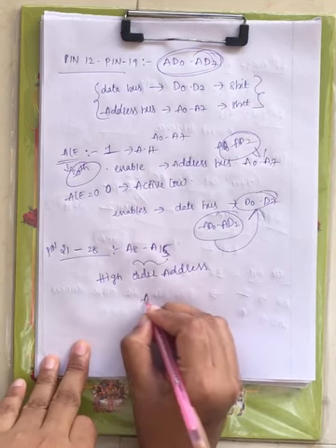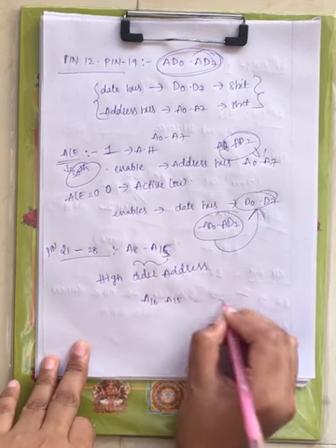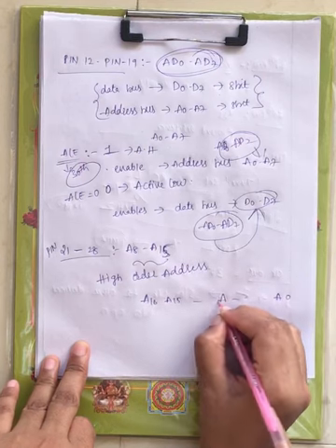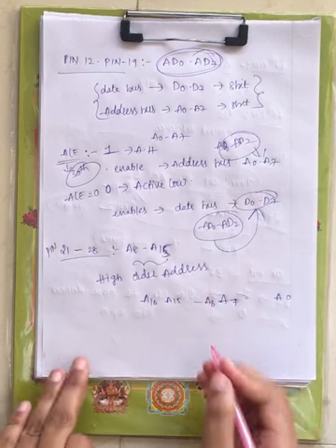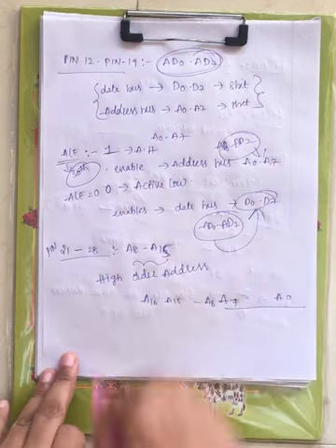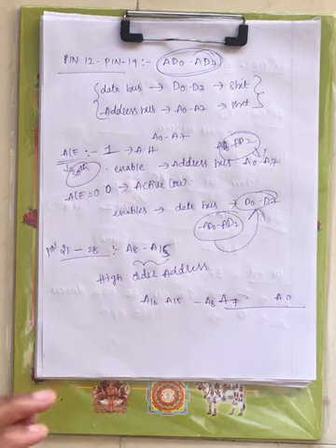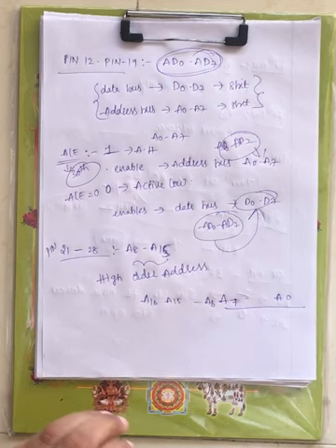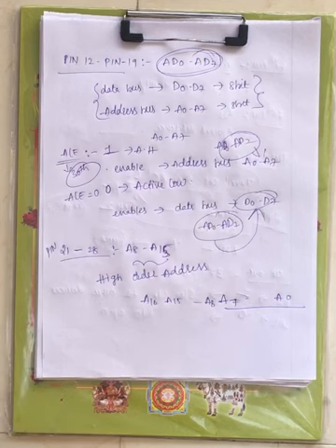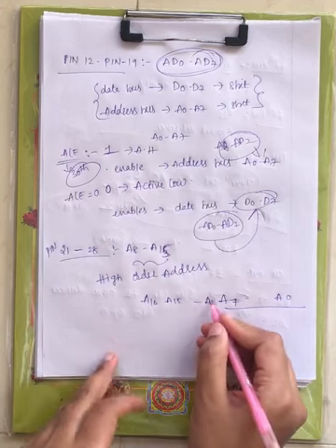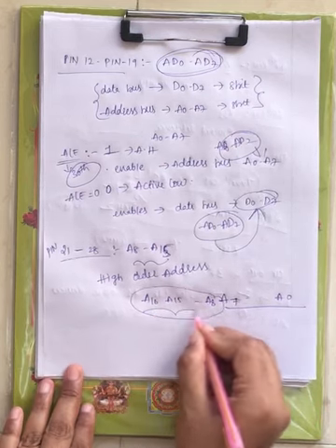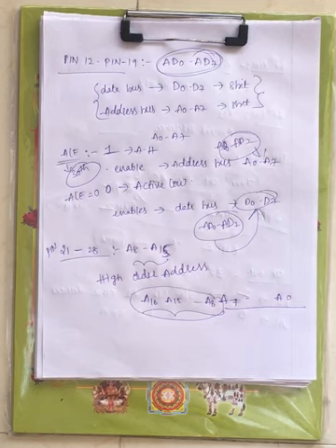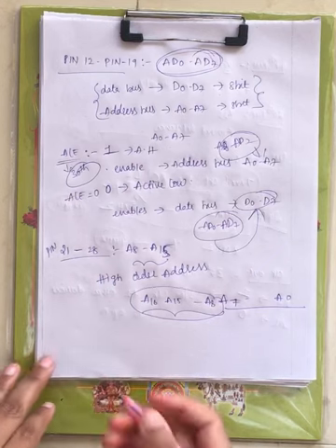Now A7 to A0 we have covered under AD0 to AD7. When ALE is 1, you can carry the lower order address through AD0 to AD7 lines. Now here there is no multiplexing of the address lines with data lines. Directly it can carry the higher order address, from A8 to A15. This is your higher order address.